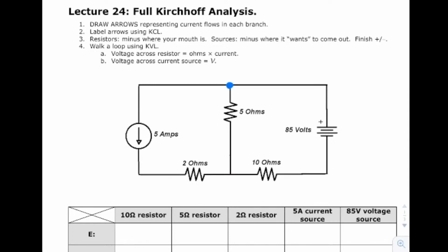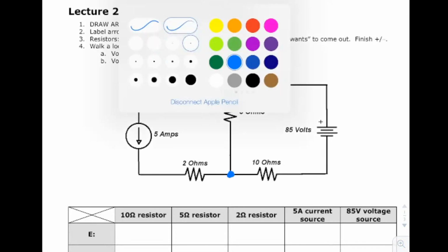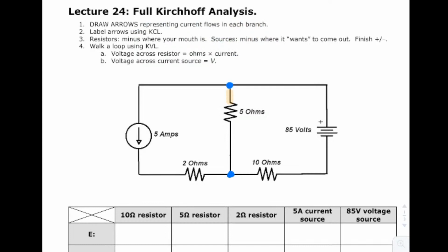This is where wires are coming together and you need a little bit of solder perhaps to keep this together. And we have a junction here. So between the junctions, it's all the same branch. So that's one branch current. Notice that over here, this is all one branch. From here to here is all one branch. And actually from here to here is all one branch as well. So we've got 3 branches here, 3 branch currents.